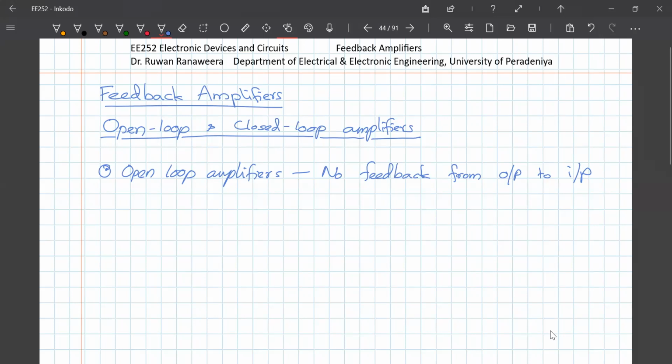external parameters. So for example, if you use feedback, you can improve the stability of voltage gain from about, let's say, 100% to maybe 0.5%. If the temperature varies, the gain otherwise would vary, like gain may be doubled, 100% variation.